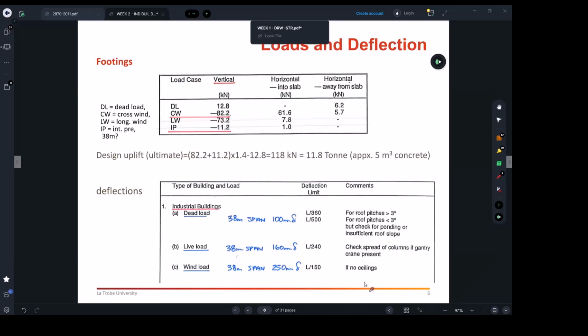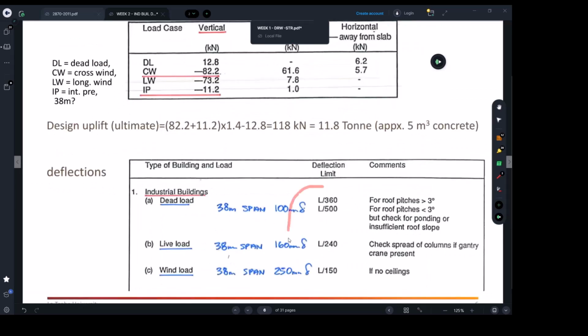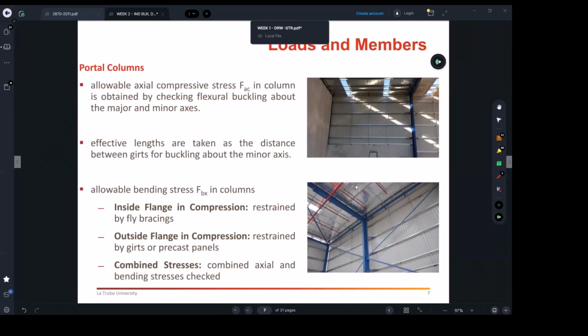You are the builder. You are the one who is really making sure everything is in the right order. If it's not working, you can go back to the engineer and tell him why this is deflected. It was written on the architectural drawings that there are units and they're supposed to be strong enough to take such deflection, because it won't be acceptable. The job can be rejected. So that's where, by the point of the information here on the slide, there are limitations for deflections to check with. Okay.